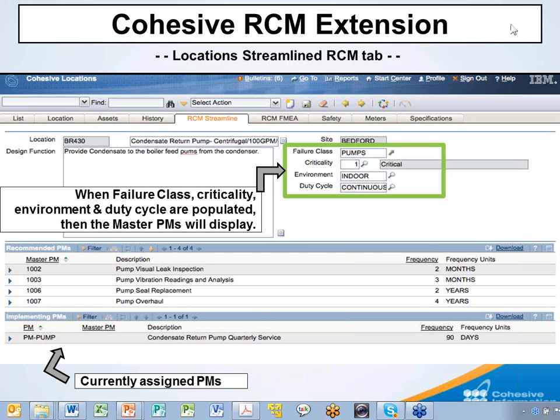And based on the as found condition of the equipment and the failure modes that it's tied to, I haven't seen any of those failure modes. The as found condition of the equipment is pristine when they open it up to do the overhaul. So I might want to extend that frequency from 4 years to 6 years.